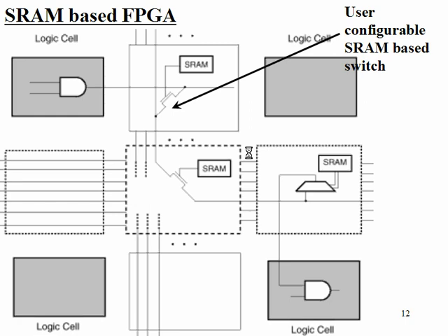This is what I was trying to explain yesterday. When you say SRAM-based FPGA, after all, what is happening? There is, of course, not an SRAM for each bit like what I showed yesterday. There will be one big SRAM. From each SRAM bit there will be connections to many MOSFETs in the FPGA. Each SRAM output will go to one MOSFET gate. Depending upon whether you store 1 or 0 in that bit, that MOSFET will be closed or open.